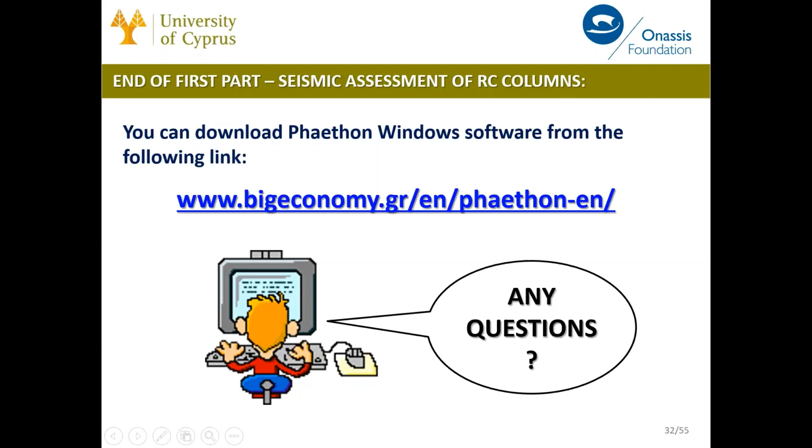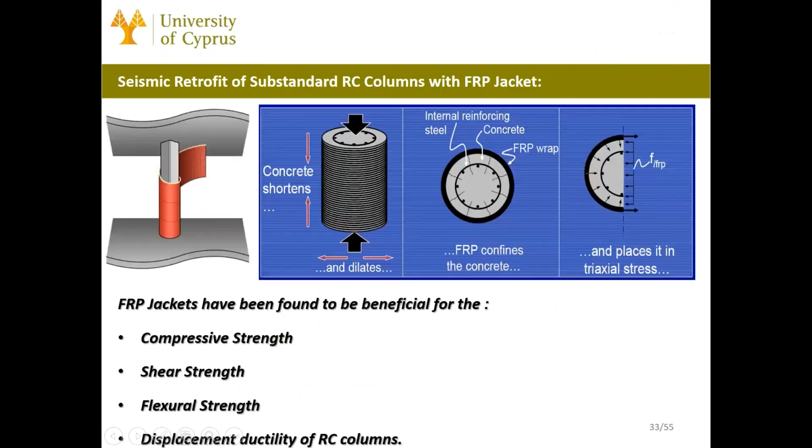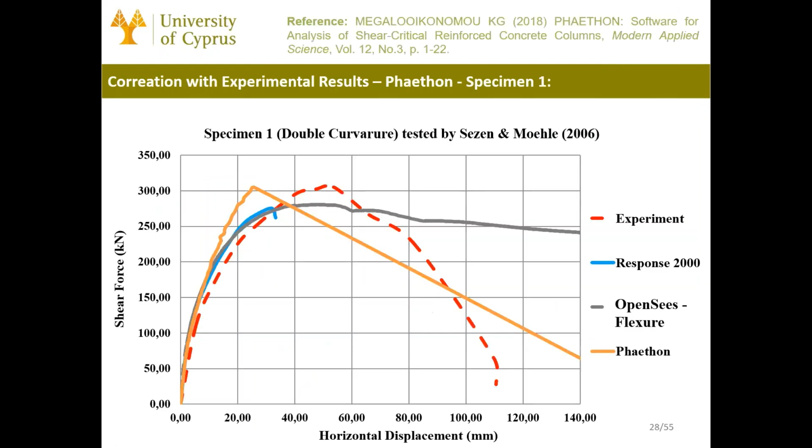I was wondering what's the source of such differences? Slide 28, yeah. Exactly, I'm comparing with a flexural fiber model from OpenSees. OpenSees has also some ways to model shear-flexure interaction, but I used only the flexural response, a force-based fiber model with Euler-Bernoulli theory that models only flexure.